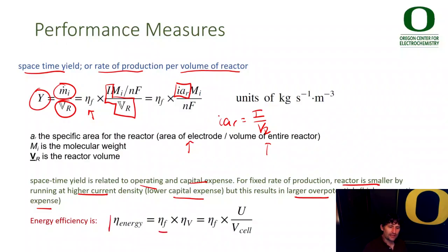It's the Faradaic efficiency times the voltage efficiency. Same thing for a battery. The voltage efficiency is just the thermodynamic voltage of the particular reaction you're driving, divided by the actual voltage that it takes to drive the reaction at whatever rate you're running your reactor.